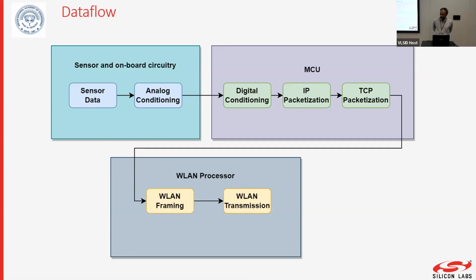So if your application has to be so small that it is no more than a button, and you cannot have a power source of more than 15 milliamps, then you use BLE. Like if you have a sensor on your shoe which measures your steps, it's either BLE or ANT. But BLE or ANT does not take you all the way to the internet. You need to connect it to your watch, and your watch may need to have Wi-Fi. So definitely BLE has its use cases.